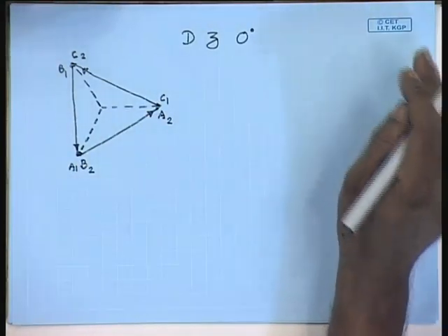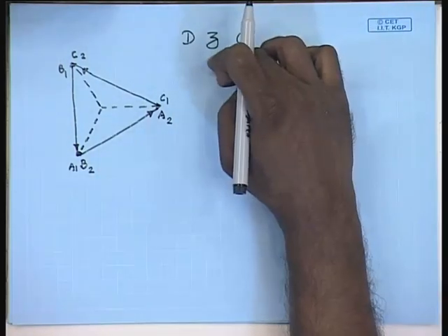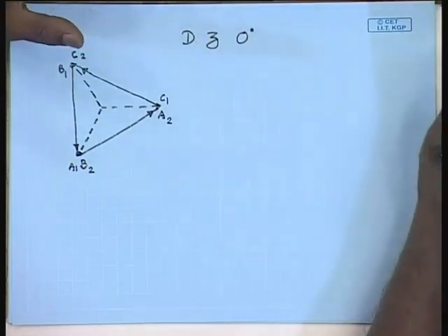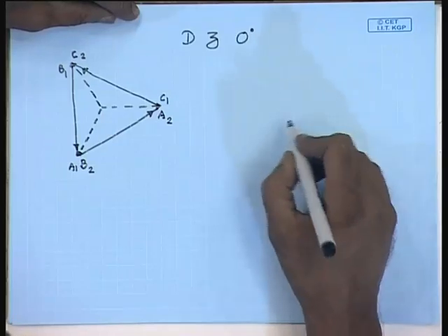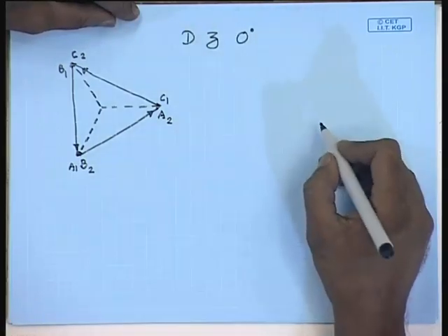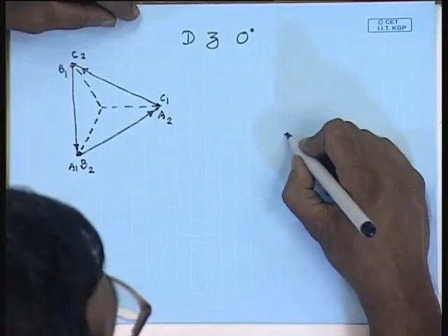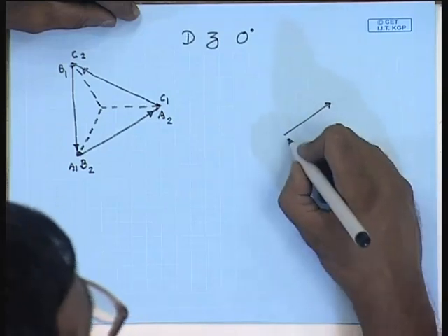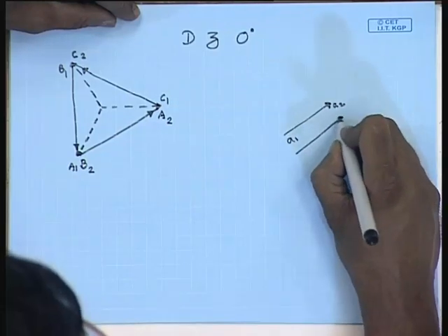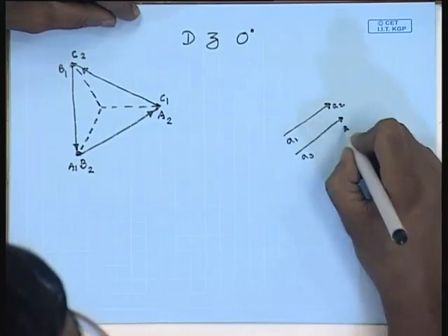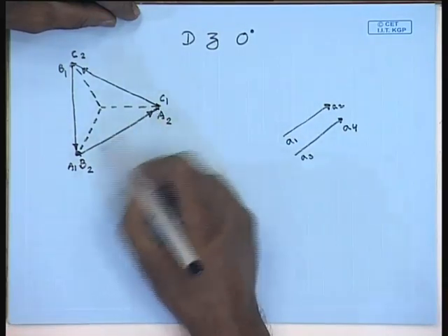Now, it is to be understood that in a zigzag transformer, each of the secondary winding has two parts. So, the voltage phasors a1 a2, there will be two voltage phasors, this is a1 a2 and a3 a4, which are parallel to the capital voltage A1 A2.